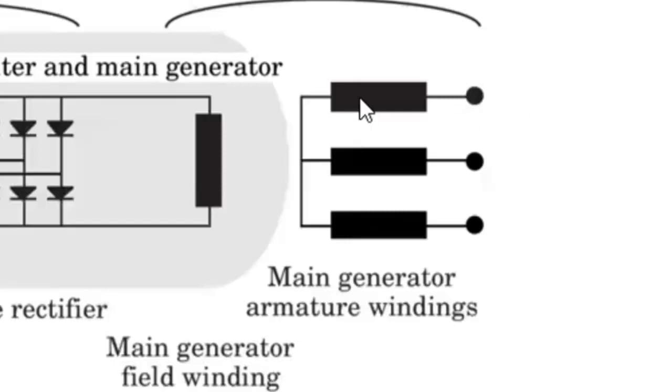Okay, which means each winding has 2 leads coming out from it. So you do the starring on the terminal block. That will mean that the start point will be accessible to you to carry out your test. So now, if you look at this, it means that you can take the resistance reading of this winding, okay,